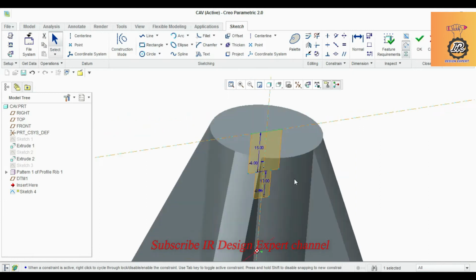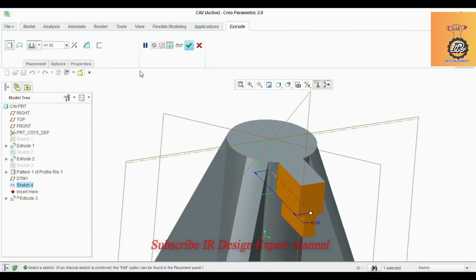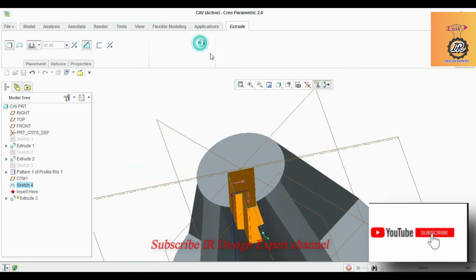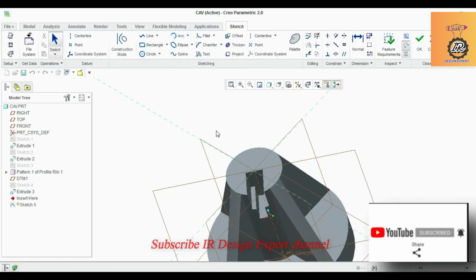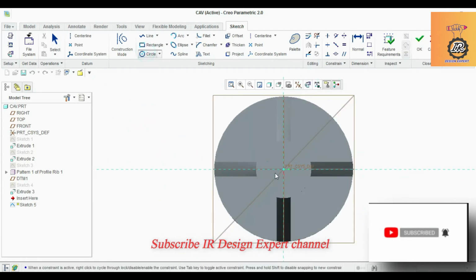and now we can make it for a cut section. So okay, extruded cut section. The cut section is created. Okay, now the top surface is selected, and then we can select a sketch view. Here you can make one circle.